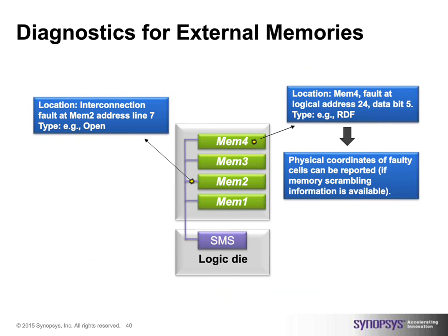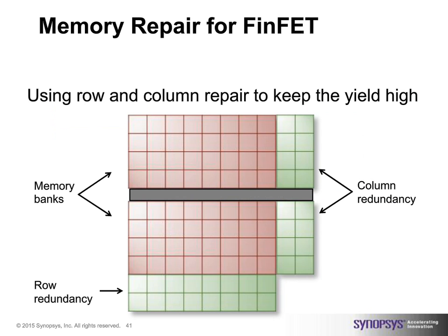Now, talking about the next step, that is repair, is important as well, because as we detect failures in the memories, we need to repair them. Now, all the embedded memories these days do come with redundancies. Often they come these days with row and column redundancies because they are needed in order to be able to fix the memory and therefore the SoC. What we do is we provide a nice solution for repair that is integrated into the same STAR memory system.